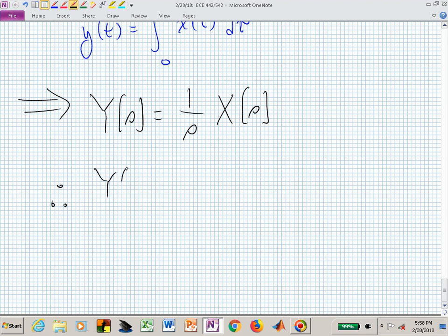This then has a transfer function of 1 over s. That's what you would expect. The integration operation in the s domain is 1 over s. We now can compare that to what we just found for the z domain numerical integration approach with the forward approach.